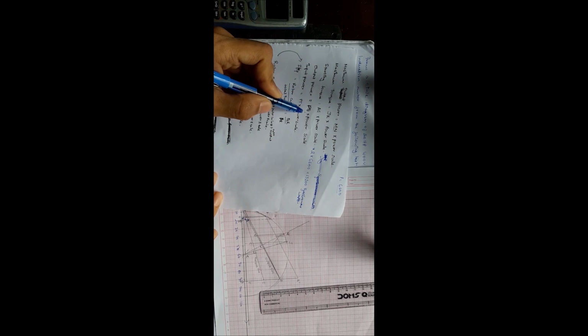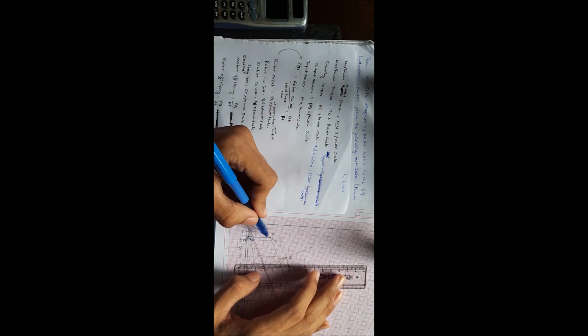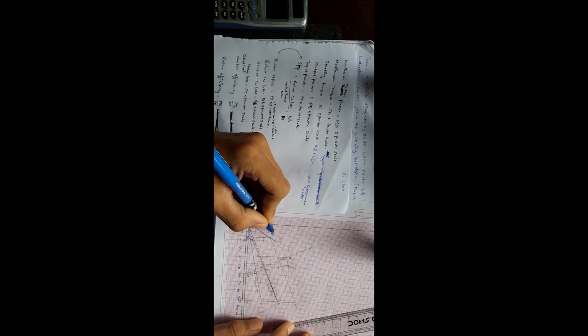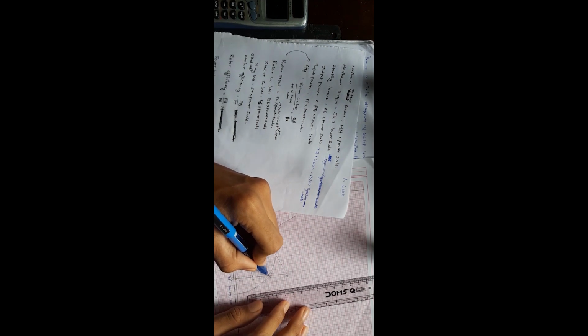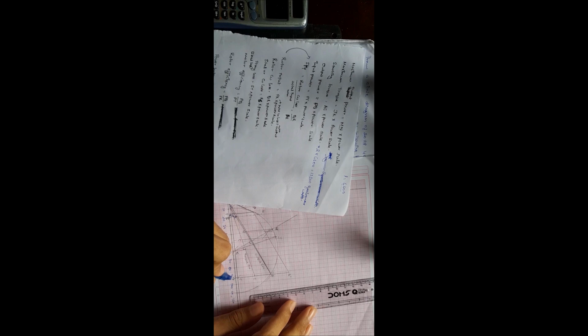The output power PQ in this diagram, if we see, this is the output power. PQ is the output power, QR is our rotor copper loss, RS is our stator copper loss, and ST is our fixed losses, which do not change. So these values are our normal condition, and these values of the losses are our blocked rotor condition, where AE is our rotor copper loss and EF is our stator copper loss, and FD is our constant losses, which do not change at any point.